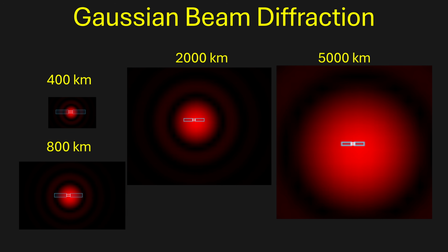Even at 400 kilometers, which is a probable cross-plane Starlink laser link distance, the spot size is only 12 meters across and barely covers a Starlink satellite's extended solar panels. On the other hand, in the military context, since the beam is so narrow and there are not wide side lobes as in antennas, the link is pretty much impossible to jam or intercept, or even to detect. If you are really paranoid about security, you can use quantum key distribution to guarantee no interception, but this is generally considered as extreme overkill and not worth the trouble.